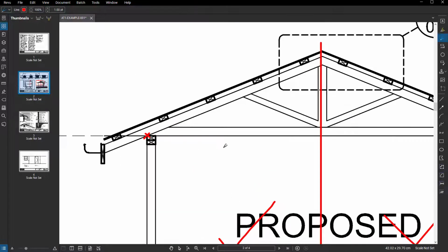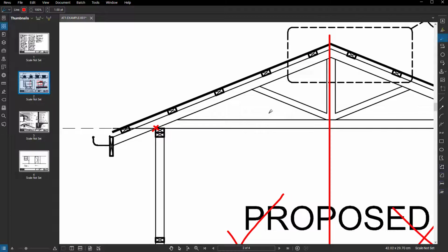And just as a reminder for standard truss terminology, we've got a standard truss here where these two lines, this zone here, is the bottom chord of the truss. This here on the angle is the top chord of the truss, and then this in here, this infill, is known as your truss webbing.